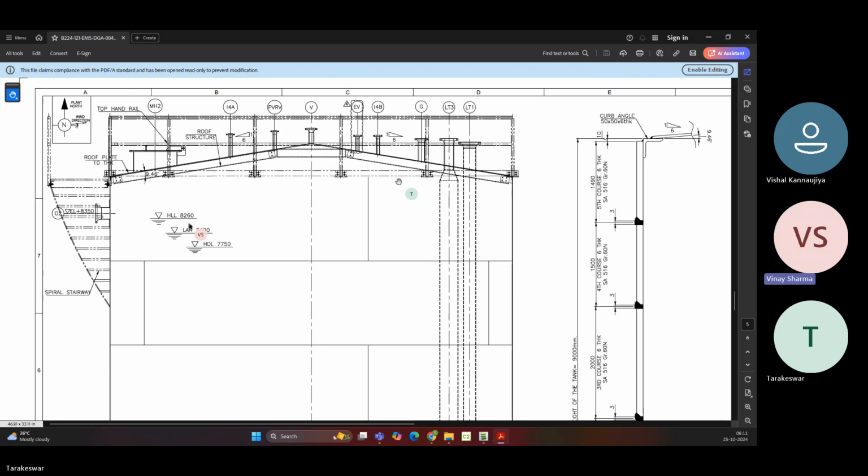Why I'm telling you this is because process has done the whole calculation. For example, if you're routing the line from this side, process has calculated that this is the line going from there, and then they calculate the loads. According to those loads, the supporting or structure guy puts the static load over there, and the stress guy marks the supports accordingly. If you change the routing, then the process loads will also change.